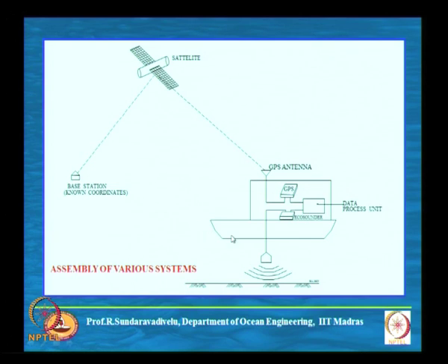Another thing is that the tidal level will vary throughout the survey period, so you have to make corrections for that also. Then there is the sensitivity of the equipment: for less than 2 to 3 meters the echo sounder will not work. The echo sounder equipment deployed below has some physical dimensions, so if it is very close to the seabed you will not get the signal. The minimum water depth it can measure below the vessel bottom is about 2 to 3 meters; less than that it will not measure.